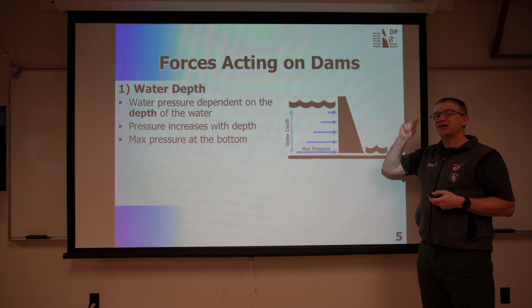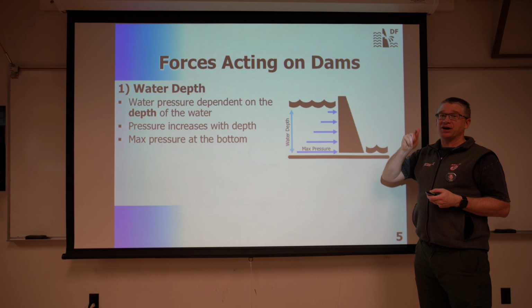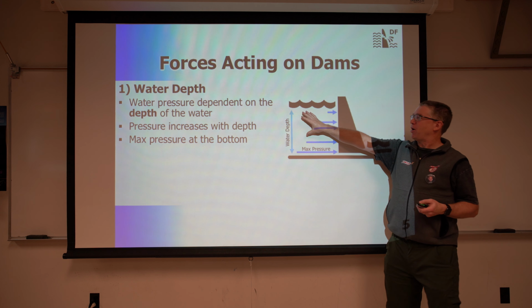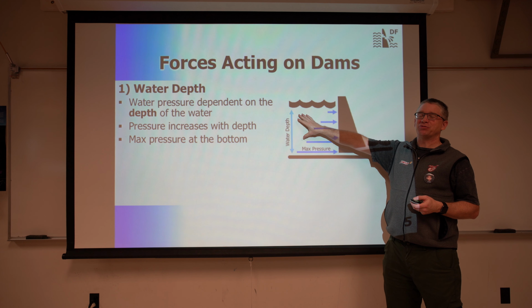It really is the height of the reservoir that is critical to understanding the design of the dam that you need. The volume of the water back here really isn't that much of an issue in terms of design of the dam.